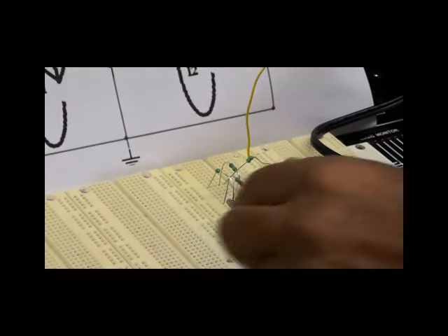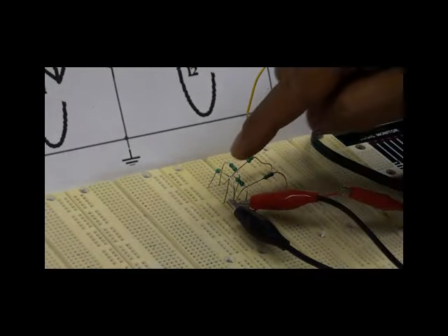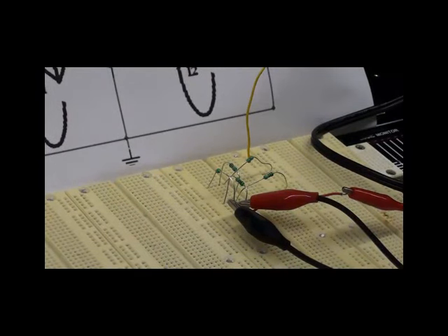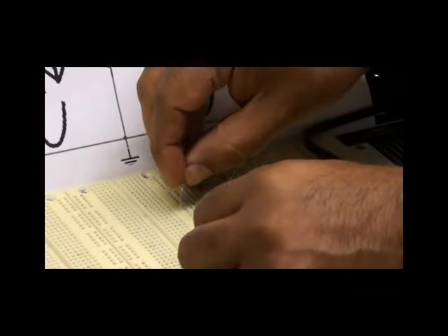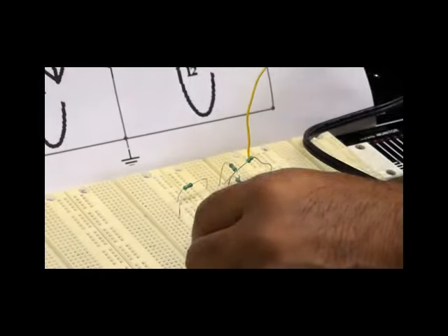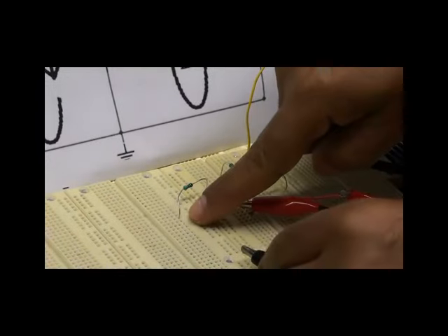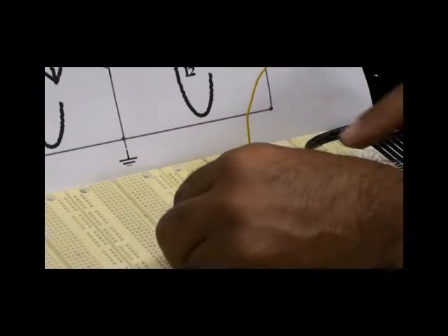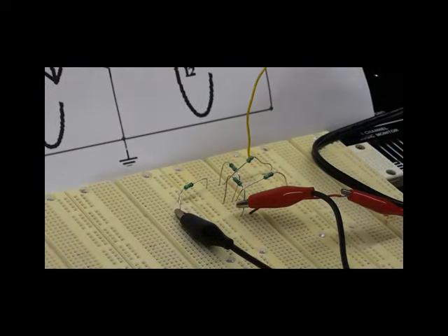I recommend that you always secure a point, not to leave any point in the air. This point is already in the air. So the professional way is just to connect it somewhere on the breadboard, let's say here, and make sure this point is not connected to anywhere, and then simply connect these two together.